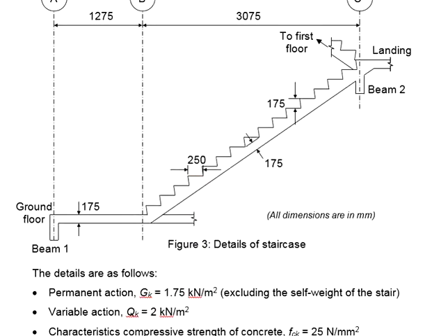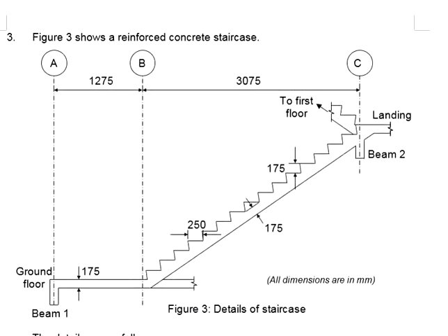The design of the staircase is similar to the design of the slab. Both staircase and the slab are large elements in an RC structure. When the member is relatively large, very often they are wider than 1 meter width. Normally, we will design on the basis of 1 meter width.